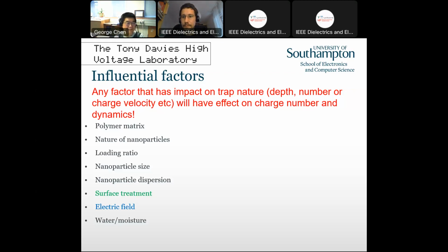Rafael, go ahead, please. We have another one that says, how would agglomerates show up in the space charge curve, as they are localized areas of high particle concentration, but not globally? I don't fully understand the question, but I guess it's about this aggregation effect. When we measure the space charge, one of the assumptions we make, at least currently, is that the charge and the system are uniform under the area of the measurement.